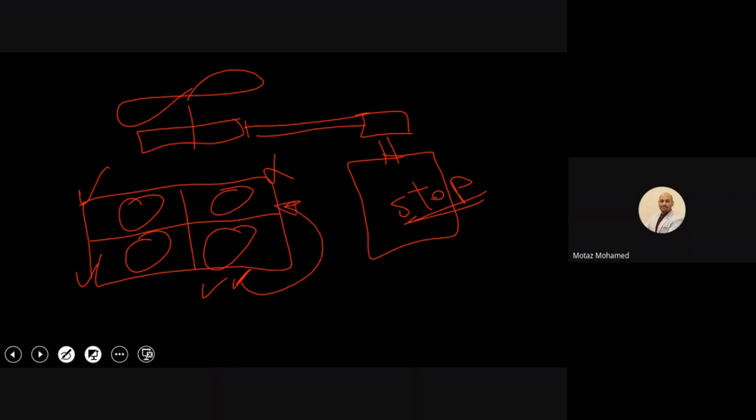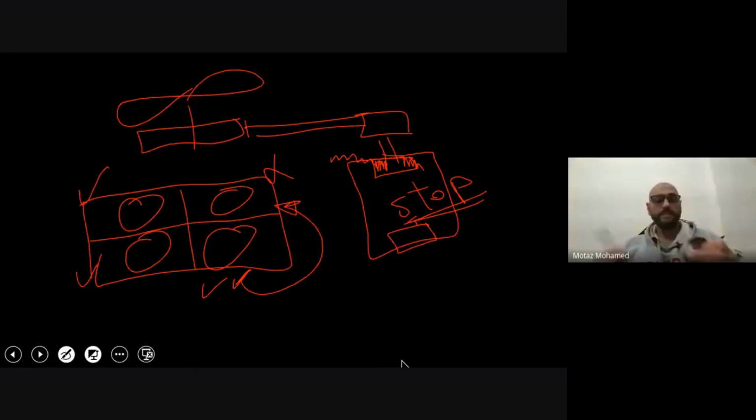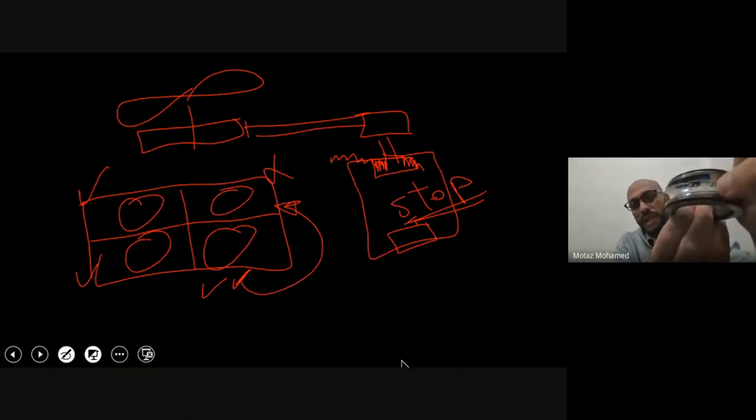And due to this transmitted vibration, the bearing here, whether it's drive end or non-drive end, starts to vibrate internally. The vibration keeps transmitting to this bearing until it starts to make this kind of dents. And this is what we actually call false brinelling. Like this, as you can see here. You can even see that the distance between these dents is equal.